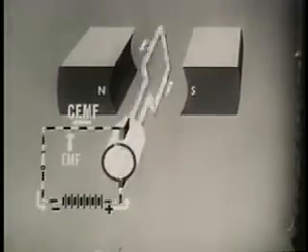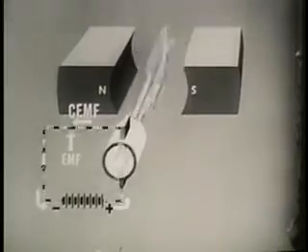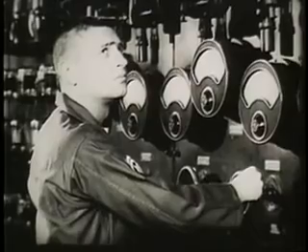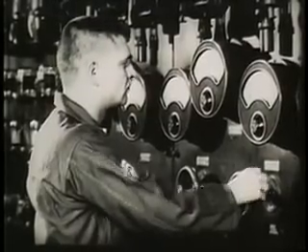This is of practical importance in large motors. When starting large motors, the problem exists of limiting current through the rotor windings until a CEMF can be built up. If the full current is applied before the CEMF develops, it may burn out the rotor windings. Starting boxes are used with DC motors in order to avoid this application of current before the CEMF is built up.